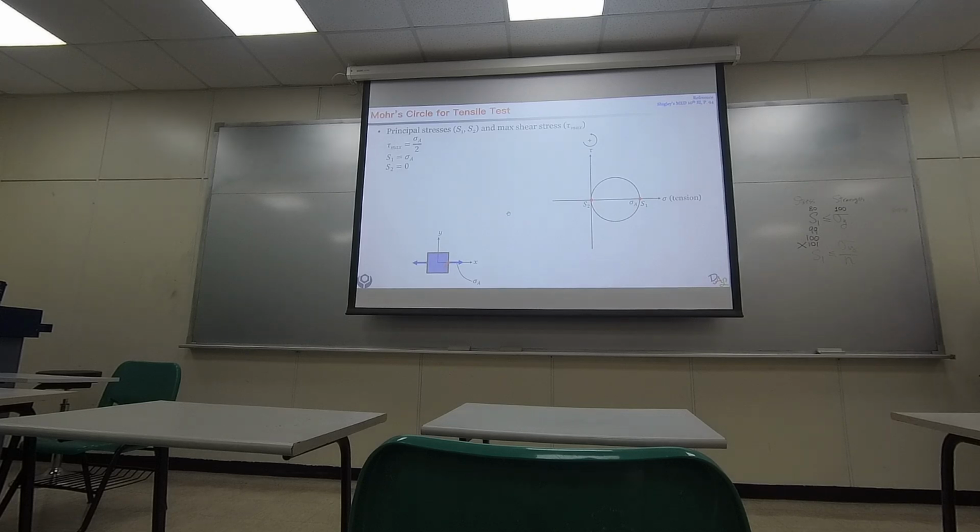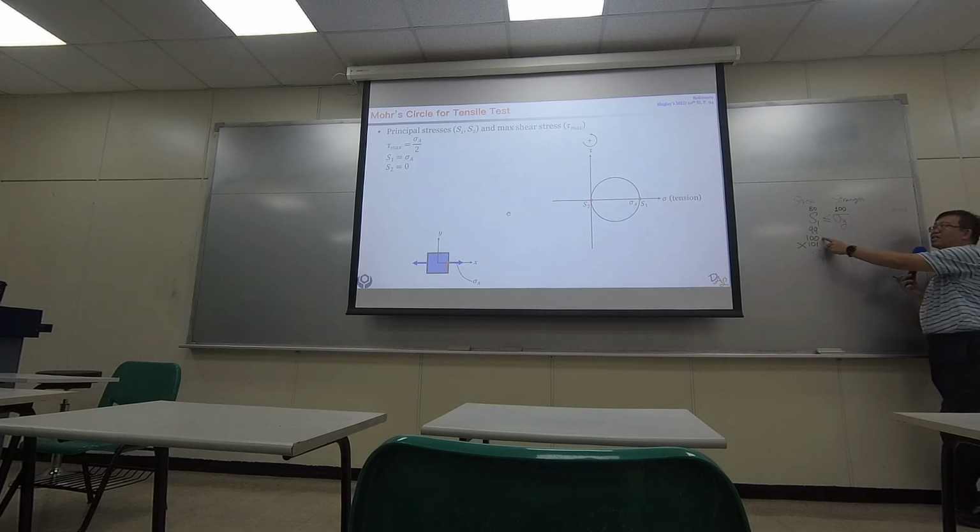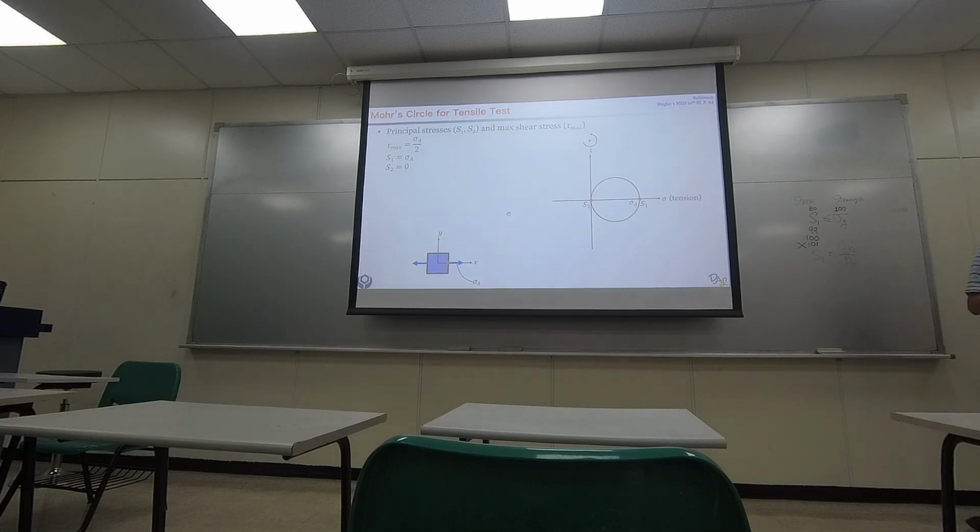But in reality, for mechanical design, we never want to see a stress that is so close to our upper limit. Because how can you be sure the material is ideal? Let's say this workpiece is made of some kind of steel, and the manufacturer already gives you a report telling you the Young's modulus of the steel.